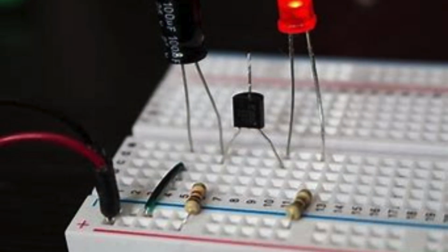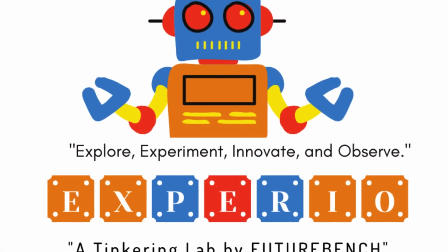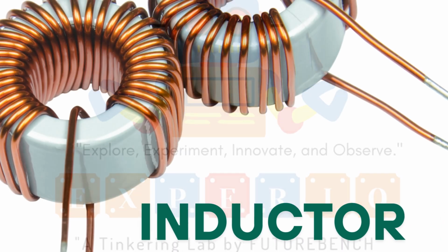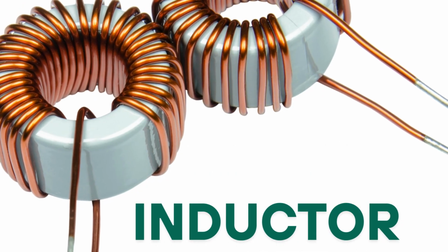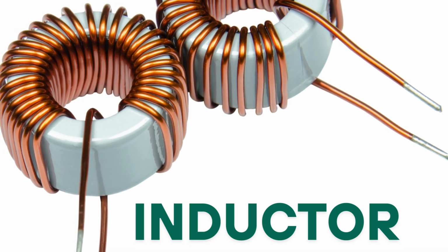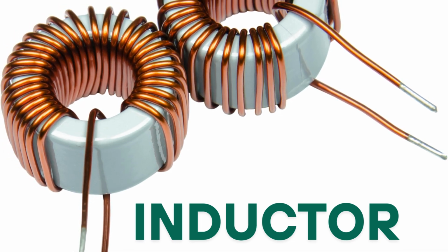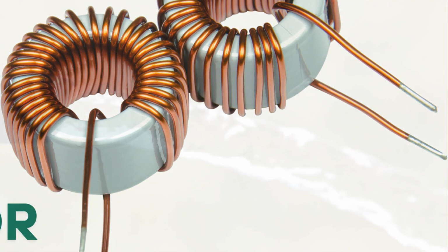Now, let's talk about the third major passive component, the inductor. An inductor is just a coil of wire, but it has a very interesting ability. When current flows through it, it creates a magnetic field. If the current changes suddenly, the inductor resists that change. It stores energy in its magnetic field and releases it gradually.